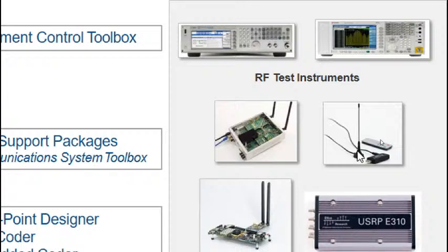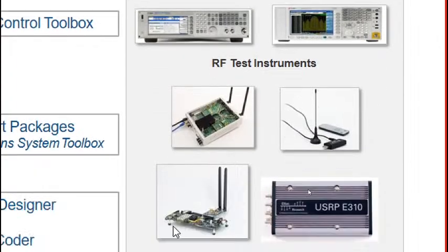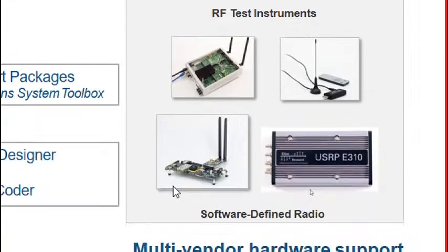This is the RTL-SDR. It is a TV tuner which used to be common, and you can purchase it for two or three thousand. There is one receiving antenna. You can interface this RTL-SDR with MATLAB and log the FM signal. You can log airplane data, meaning track the airplane. Whatever is feasible and allowed for you, you can log that data in MATLAB using this RTL-SDR. There is also the ADALM-PLUTO, which has both a receiving and a transmitting antenna.